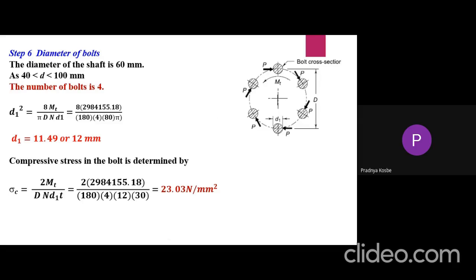And here, according to force direction, you can see bolts are subjected to direct shear stress due to the force P and not torsional shear stress. So no torque is acting about the axis of the bolt.